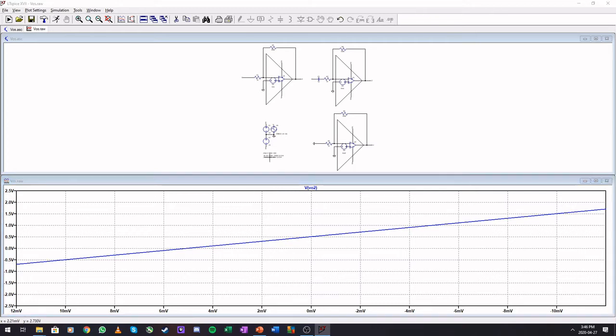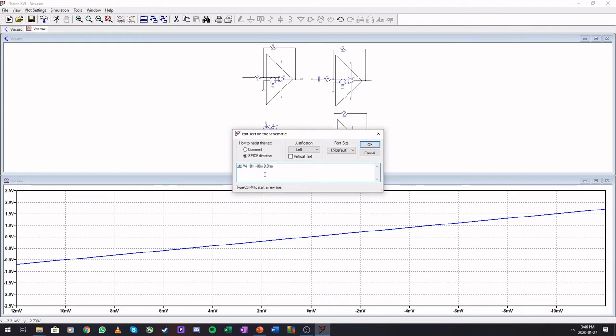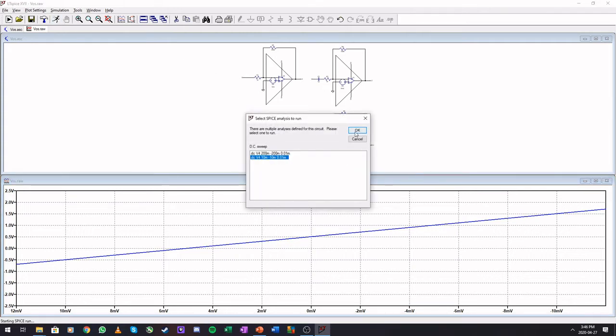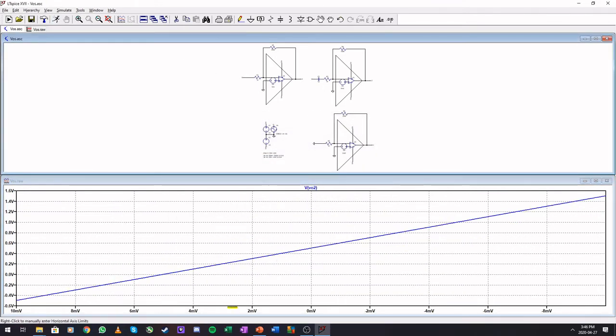Okay, so if I just do this second DC simulation, I have made the range a bit smaller. We can see this kind of nicely. So here at 5 millivolts, our output is at 0. Sorry, here. And at 500 millivolts output, our output is right here. Okay, so you can use DC sweeps in simulation to kind of find the offset input and the offset output. That is a very nice way to find these.